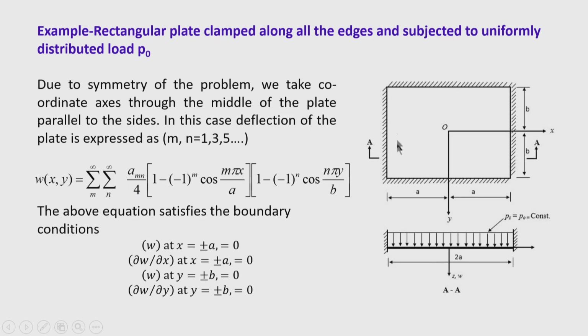Now, this problem actually was not solved analytically, and the analytical solution was not found readily for that kind of problem. However, this problem can be solved by the method of superimposition using Levy's method with edge moment. So, application of edge moment can give one result, and then it can be used with a simply supported plate with uniformly distributed load.